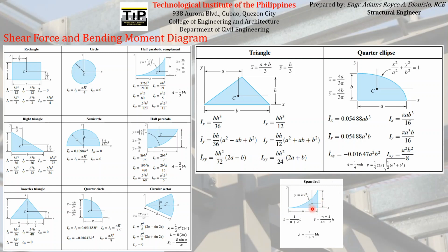If we memorize the formula on how to find the corresponding areas under these common shapes, or inside these common shapes, we don't need anymore to integrate. So we can use this as a supplement on drawing the shear force and bending moment diagram. So you have to memorize this. You have to be familiar with the different formulas of the different common shapes, which are again the usual shape of the load diagram, which the beam usually carries or supports.